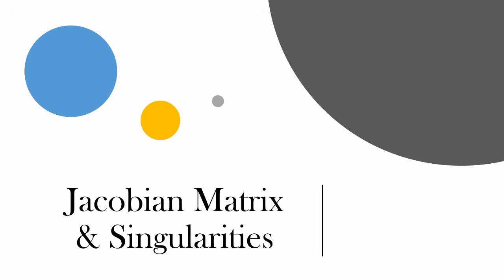So the Jacobian matrix, or a Jacobian for short, is used in a variety of fields in mathematics and physics, but here in robotics, we will use it mainly to find singularities, the forces and torques that can act on a joint, and the joint velocities.